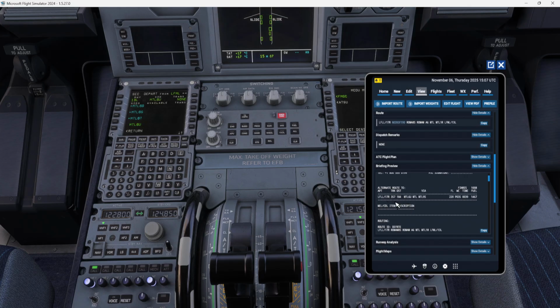So we need to get a track of 357. Okay. Then we go to airport again. We click on it. We go down until LFLL. We have MTL 9 Sierra runway 17 right. Okay, so we get a VOR 17 right. MTL 9er Sierra, this one. Let's return, and then let's go to the Black Box website to get our engine out SID.